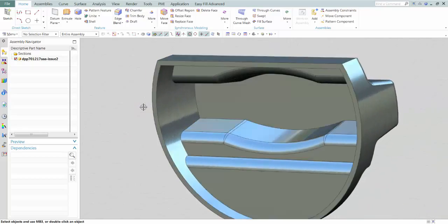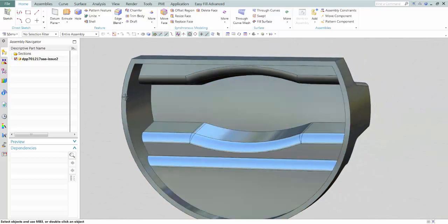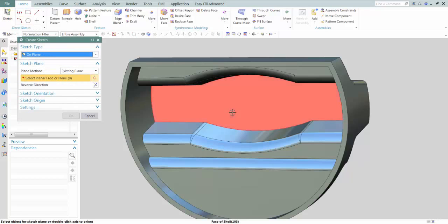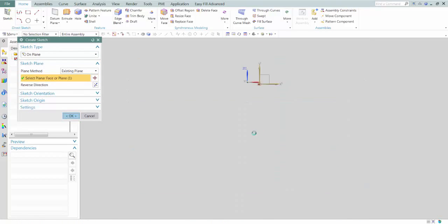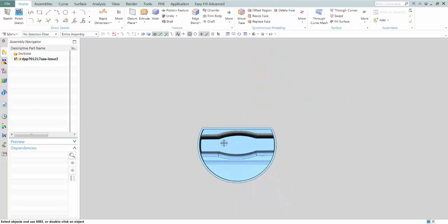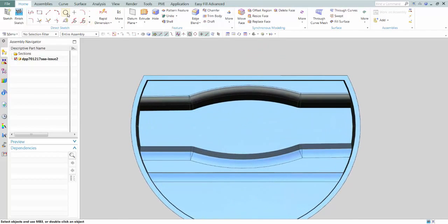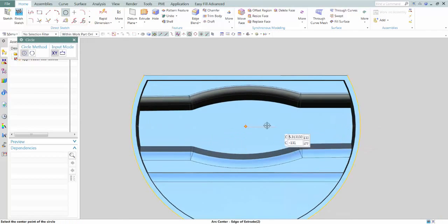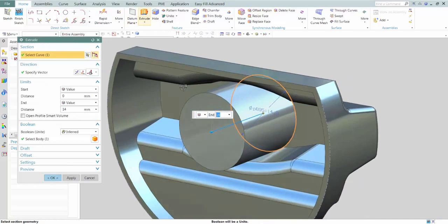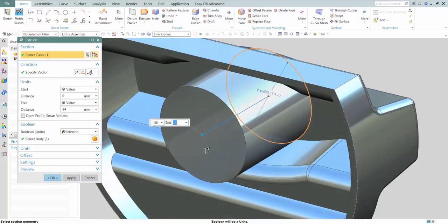Now if we flip the model over on the inside, we may want to put some strengthening ribs, give this a little more strength on the inside. So I'm going to go out and just create a very quick sketch. I'll just tell it where I want to draw something out here on the screen. And as we go in and look at this geometry, I may say, well, I'm going to draw a circle, and we'll just center it in the model here and give this some size that we may want it to be. And what's nice is NX understands that you may want to go ahead and just create that as some geometry. So I'll do so.